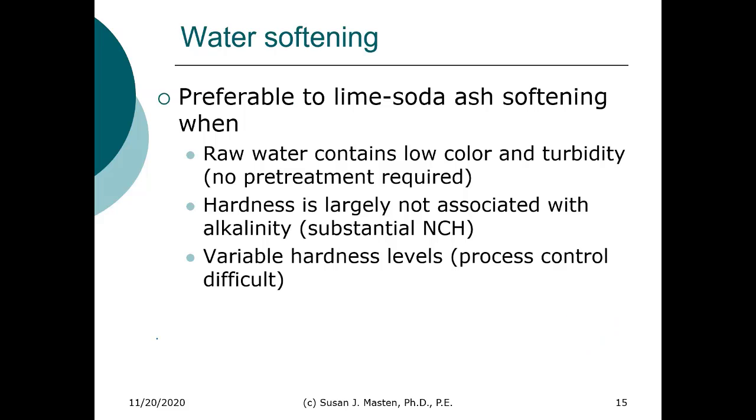So the last slide that I'll show today is the question: when do we use ion exchange over lime soda ash softening? If it was a normal year, we would visit the Williamston water treatment plant. It's about a 2 million gallon a day plant. They have ion exchange, versus East Lansing, which is about a 10 mgd plant, or Lansing, which is about 40 mgd, where they have lime soda ash softening.